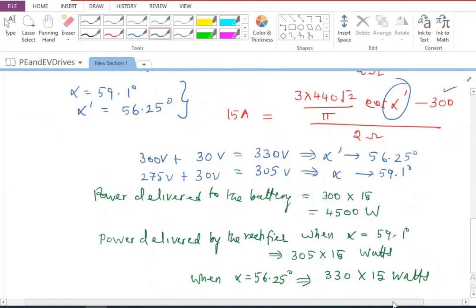Then we had looked at fully controlled rectifier with SCR in single-phase case as well as three-phase case. We had looked at waveforms with R load, RL load, RLE load. I would urge you to do a bit of simulation so that you understand these concepts very clearly. I have eliminated completely semi-controlled case because we are not going to look at them much in battery charging, especially when we talk about electric vehicles for electric vehicle application.